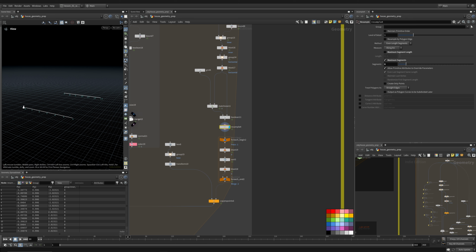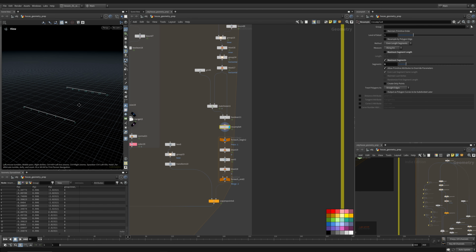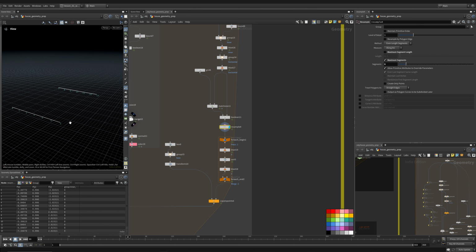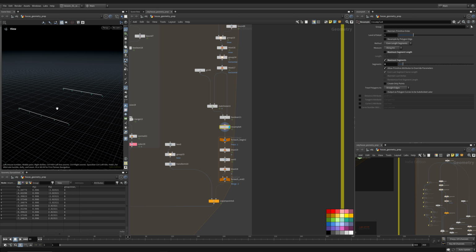And if I deleted point 0 and point 13, then that would leave 7 and 6 without being deleted. The reason I can't manually delete those is because I don't know how many points there are going to be. And I actually could probably reference the segments and write some VEX to delete those points, which might be easy, but the way I chose to do it was to do a for each loop.